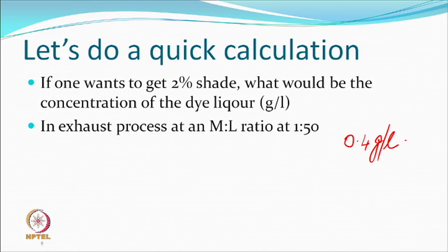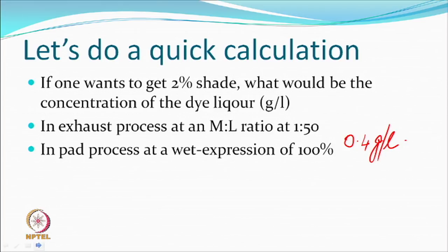Let us say in the other process, which is called a pad process. So, what do you do in a pad process? You have a dip and a nip, padding mangle. You have seen that padding mangle? So, in a pad process, what will be the concentration of the dye liquor if I want the same thing at 100% expression?